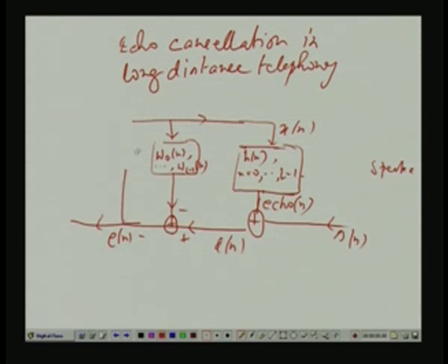And if I use the e[n], this is a symbol to adjust the filter weights by the LMS algorithm. So they are adjusted by the LMS algorithm by this e[n]. What will happen? If everything else is done properly, the filter weights will finally converge, at least in the sense of mean, to this h[n]. If the misadjustment is very small, what will happen? They will actually converge to h[n], but with a very small difference.